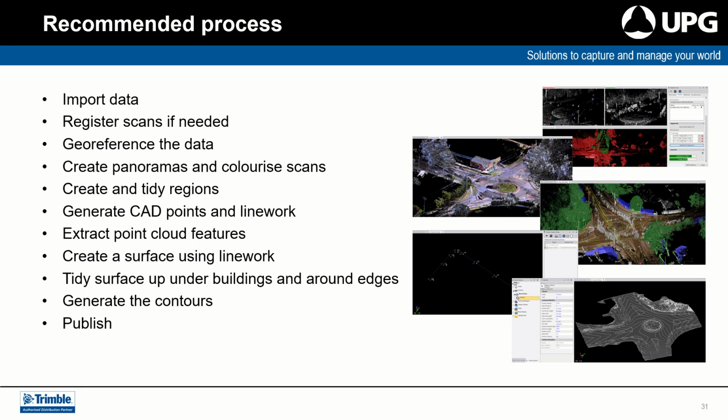When generating the surfaces, remember that the surfaces are generated from all the selected data. So if you have things in your project that you don't want, then you just simply would not have them used when creating the surface. There are also tools, once you've created the surface, that allow you to add and remove points. So if you went back and digitized some data afterwards, you can add them to your existing surface. You can remove points that are creating spikes or holes in your surface as well. You can also edit the data and recalculate the surface.